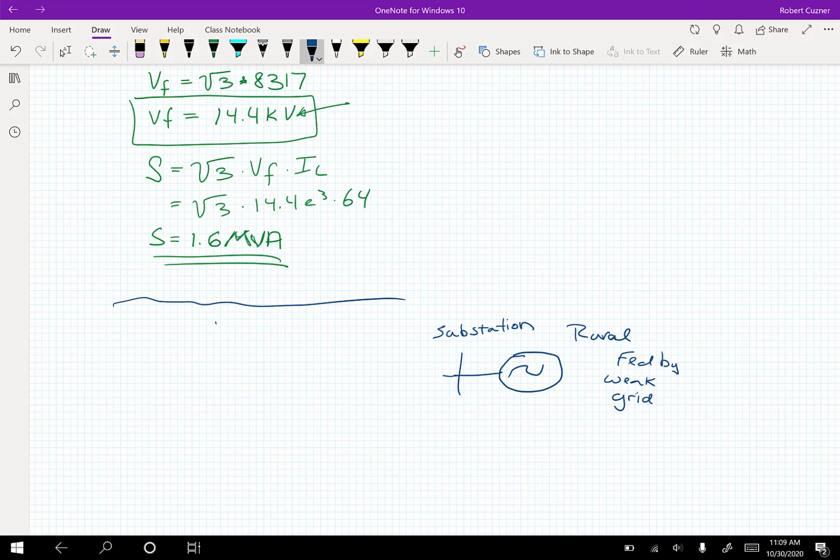So at the substation, you're going to have a transformer. It's probably a Wye-Delta because it's a big step down. There's a big transmission line. So your typical feed right here might be something like, let's say, 24 kV is your nominal. That's what you're hoping to get, right? Nominal feed.